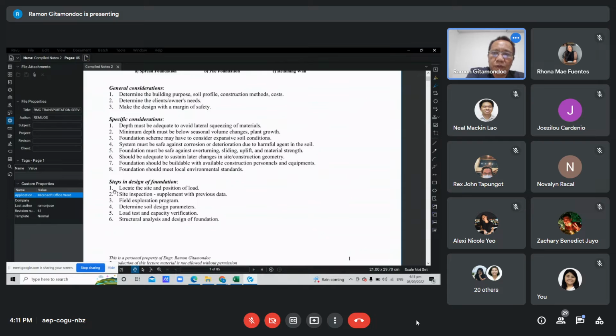Like for example, in densely populated or commercial areas, it is discouraged to use driven piles using diesel hammers, because those pile driving methods create a lot of sound, smoke, and also vibrations which could damage adjacent structures. So if you are designing there, you don't recommend driven piles. You should look for other options. Another option could be the use of bored piles.